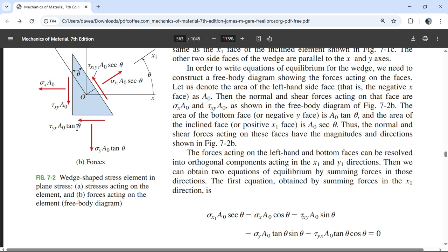cosine theta. And tangent theta cosine theta is sine theta, because tangent theta is sine theta divided by cosine theta. And then I'm going to multiply it by that cosine theta component, which is the sine of phi, they're complementary angles. So sine theta divided by cosine theta multiplied by cosine theta. So this just becomes sine theta. So I have negative tau yx a naught sine theta. That's what I should see down here. Where do I see it? Tau...